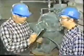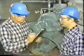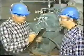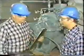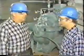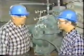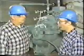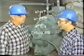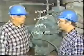Well, Gene asked the same types of questions. The operator told him there was too much runoff. The runoff came from around the gland follower. The excess leakage appeared only at the outboard packing, not at the inboard packing. The operator first noticed an increase in leakage 2 or 3 shifts ago. The leakage has steadily increased since then. The operator tried tightening down the packing gland, but that didn't seem to make much difference. And at that point, he reported the problem.